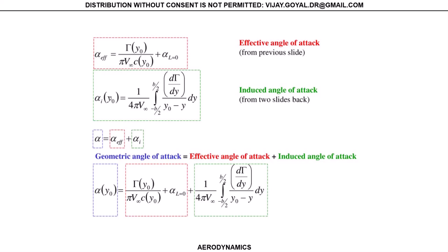So just to summarize a few things, this is the angle of attack, this is the induced angle of attack. We will work with each one of these components in the next couple of charts. But this is giving you a general overview of this, and so the total angle of attack is equal to the summation of that. And what we really need in the airfoil is the effective. So what I did in the previous charts, I call this R. So this will be alpha minus the induced angle. Okay, and this is the addition of that.